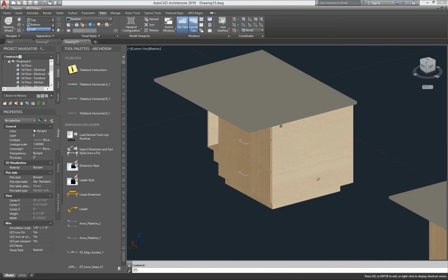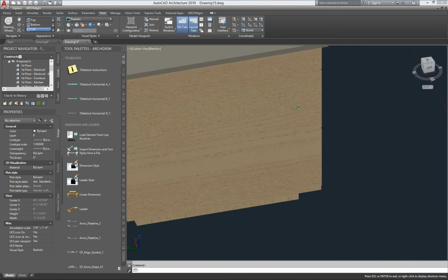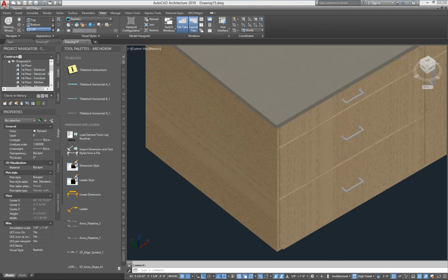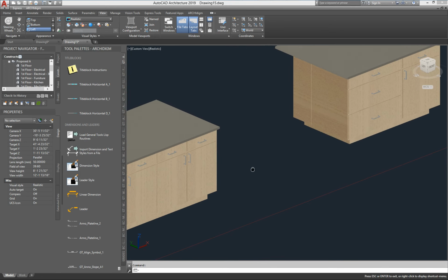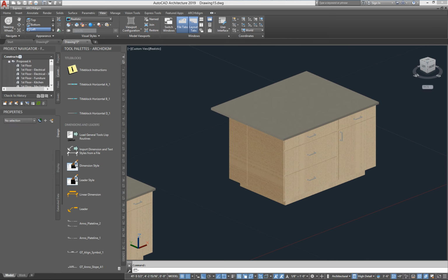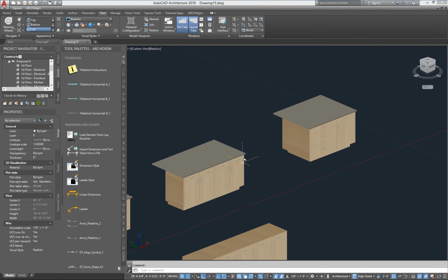But that little trick of using global will fix any issues with material mapping if you run into that. It may create other problems, which is why we don't have that as a default. We try to have the mapping mostly as face mapping in our solutions.